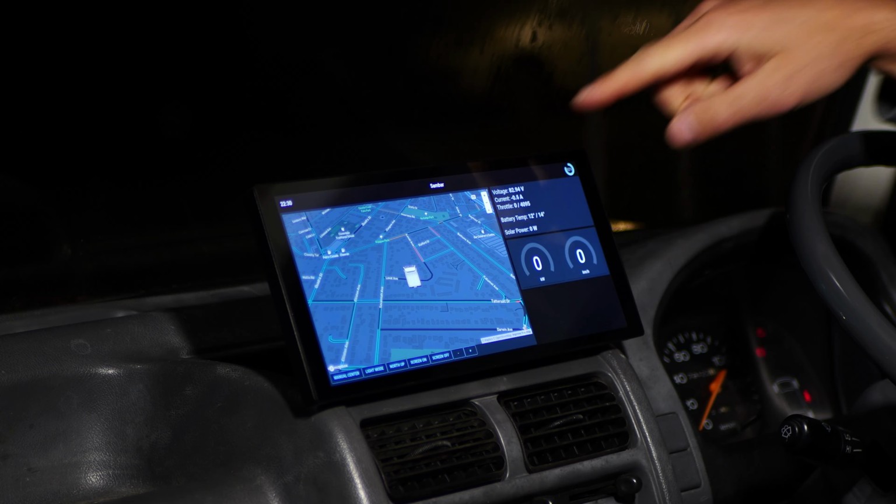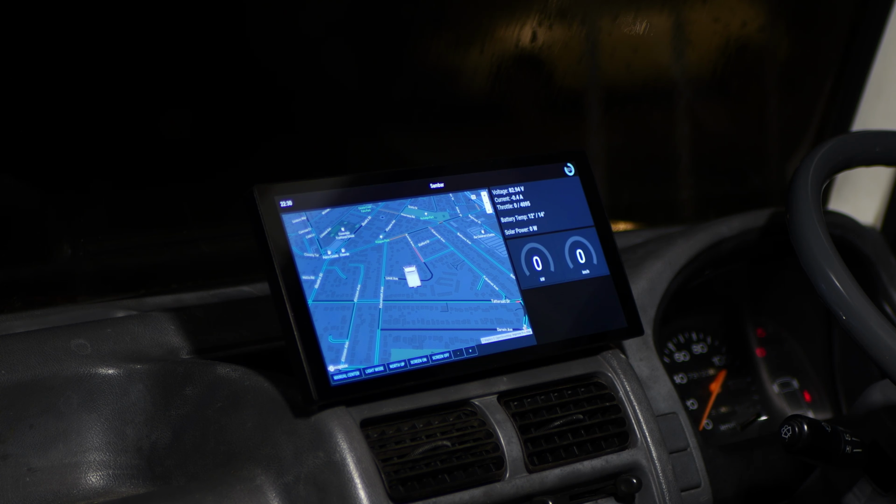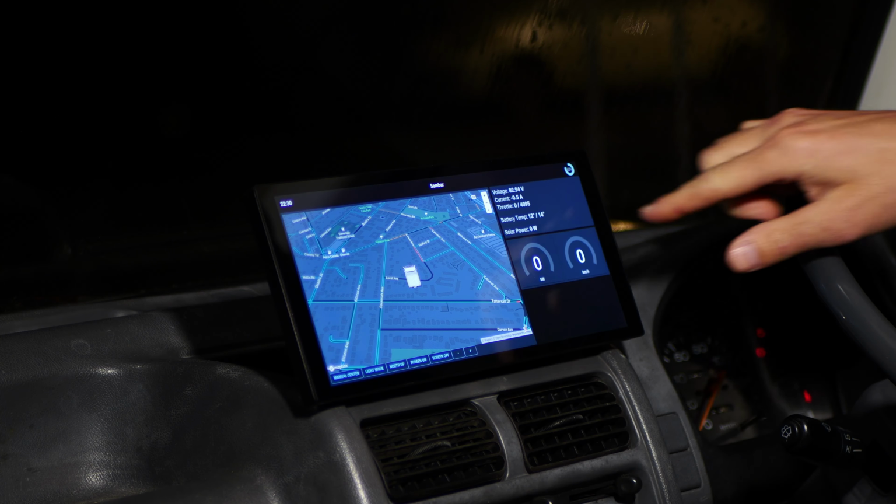The current measurement is what's flowing through the shunt. We have the throttle position from the motor controller, and then the actual temperatures from the thermistors and the batteries. If it was daylight, you would get some amount of solar power coming in. At the bottom we have two gauges for kilowatts of total battery power, and then speed in kilometers an hour.